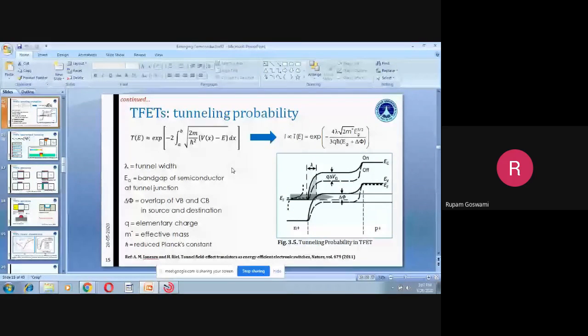It is very intuitive that you select the parameters you have calibrated at room temperature and then go on with the rest of your simulation. But I would recommend that you do not blindly take the values for room temperature and apply them to other temperatures, because there may be many other phenomena related to that. Okay, so hope this answers your question.